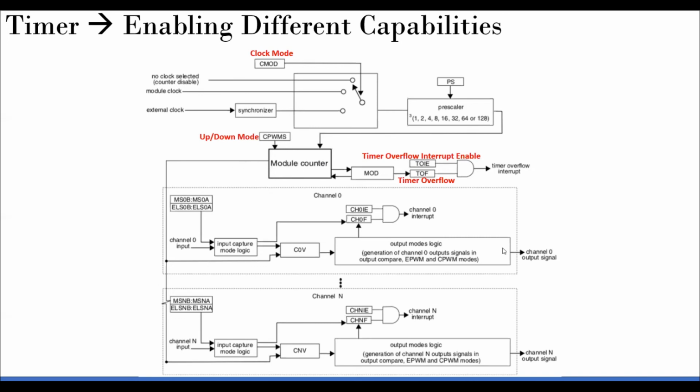So then these are the individual blocks. So many channels are there. Each channel output can be given to a certain port, for example GPIO. This is mostly for the output side, the PWM, for example. So different channel options are there. You can go and see how many channels are there for our board. And this is the other side, which is coming from the polling part. If you want to poll some channel, you can do that as well. You connect that GPIO to this channel, and it will poll that. So this is the capture option, and this is the compare option.